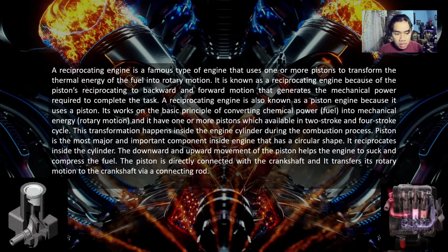The piston is the most major and important component inside the engine, and it has a circular shape. It reciprocates inside the cylinder. The downward and upward movement of the piston helps the engine to suck in and compress the fuel. The piston is directly connected with the crankshaft, and it transfers its motion to the crankshaft via the connecting rod.